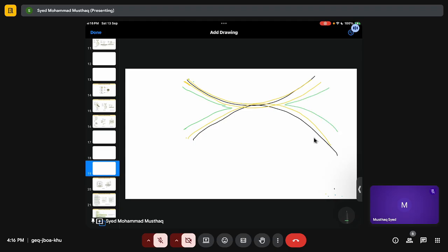And this polarization will not stop, and because there is very high voltage, whatever is polarized will again polarize the nearby molecules, right? Because this guy has plus, and this polarization will result in minus plus, and this plus will again attract the minus of another molecule, right? So more and more polarization will happen. So at a point, everything is getting covered in charges. So once you have charge,